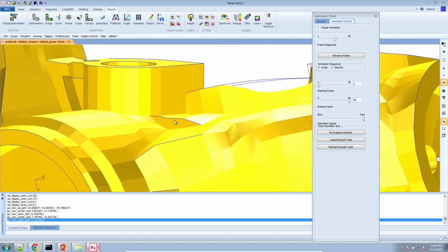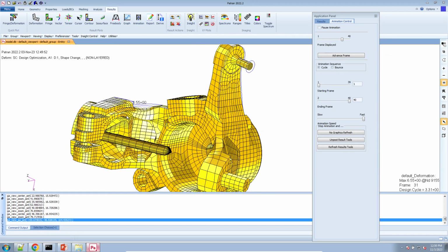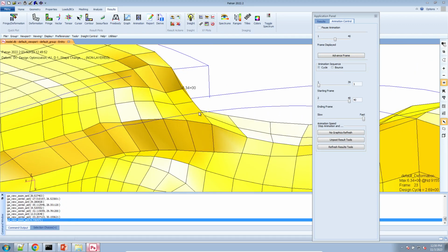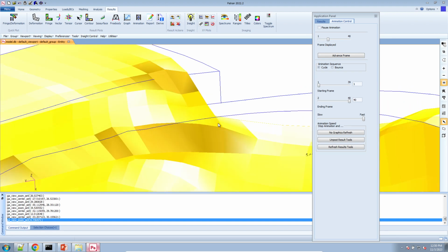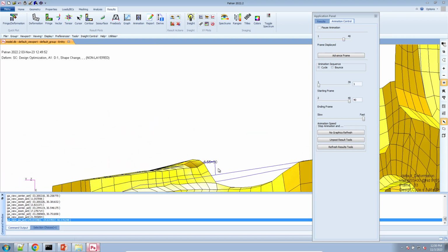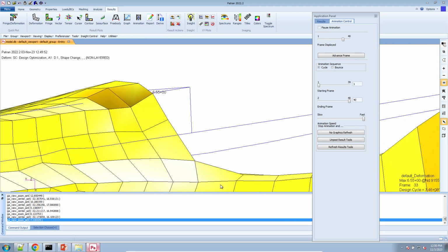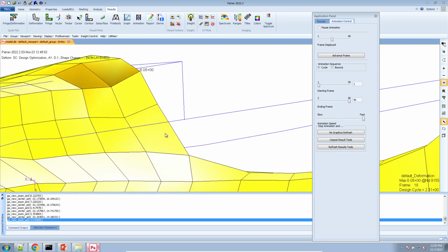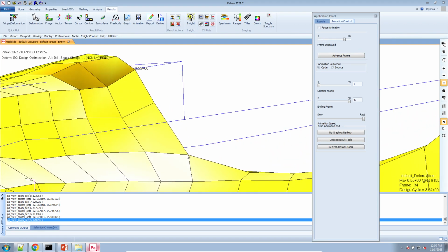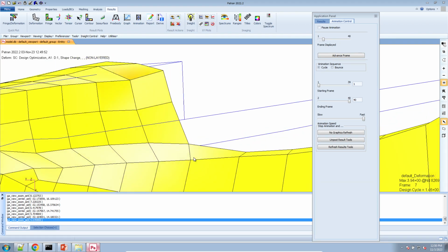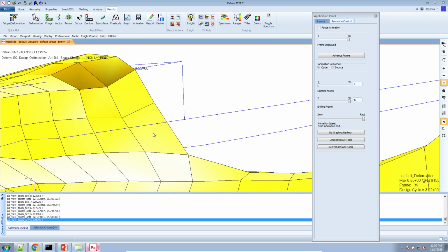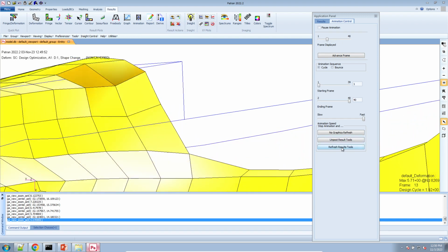Here, one comment to make. In a moment, I'm going to show you that this element here was the element with the high stress value. You can see what the optimizer has decided to do. To make sure that the stress is low for this element, it's actually decided to smooth out, for the most part, that corner. And it's when you smooth out that corner that you're able to minimize the mass while at the same time making sure the stress is within the upper bound of 40, I believe.